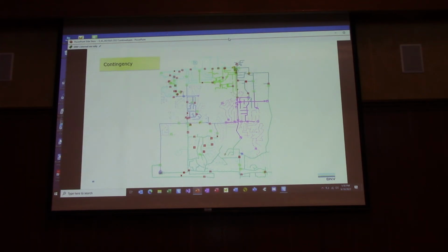Okay, so I think we're almost to the end of this thing. Contingency analysis. We've had it forever. It's a very good tool, something we work on all the time to make it better. The thing with contingency analysis is it does not deal with DER. And so that ride-through that I was talking about, coupled with contingency analysis, is going to be very important. Right, so you can see, all right, we do this switching, we lose these generators. Or if we're going to do this switching, we lose the generators, and then they come back on in our final state. There's all sorts of problems, issues that could come up with generation that we have to deal with in contingency.